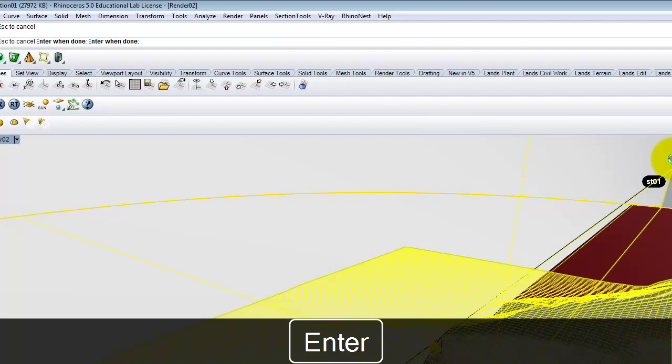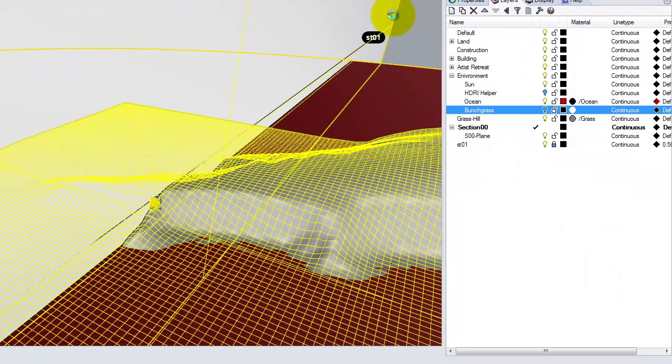And so this process takes a while, and what it's going through is it's trying to split every single one of those surfaces right along that section line. It should work for almost everything. If you have a piece of furniture that you brought in or something that's a mesh object, not a regular NURBS Rhino object, you may have to do split mesh instead of just split. So we'll give this a second to finish.